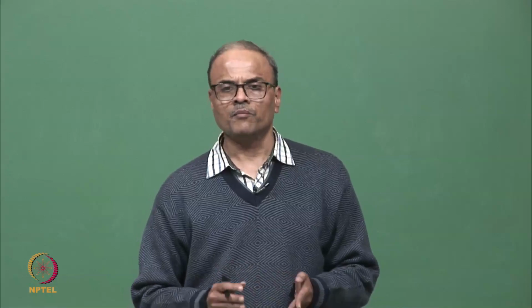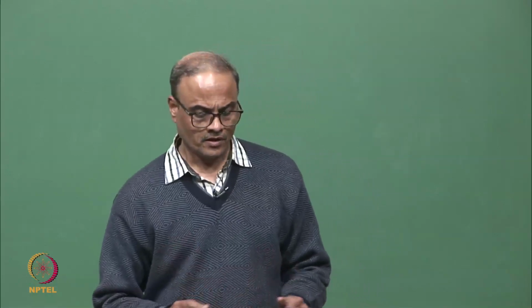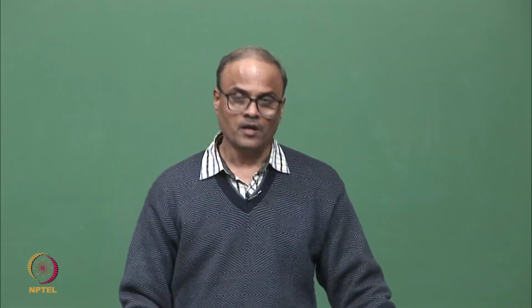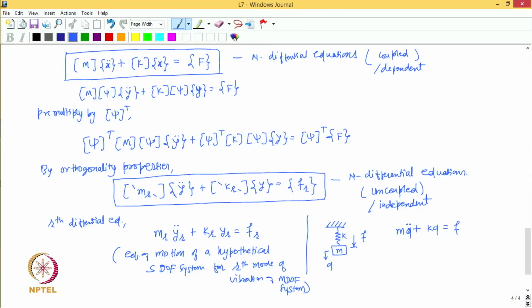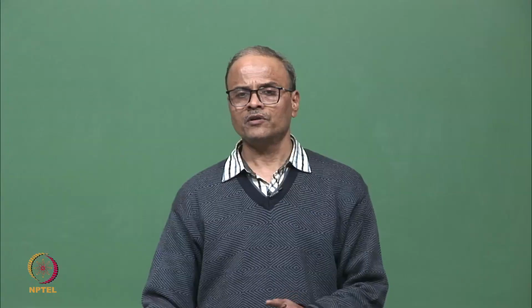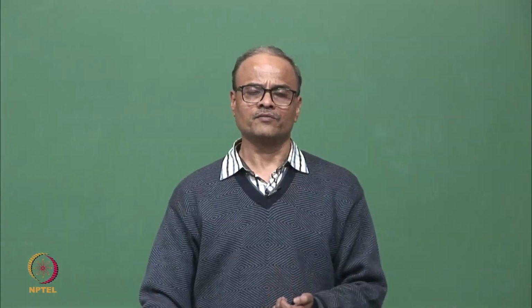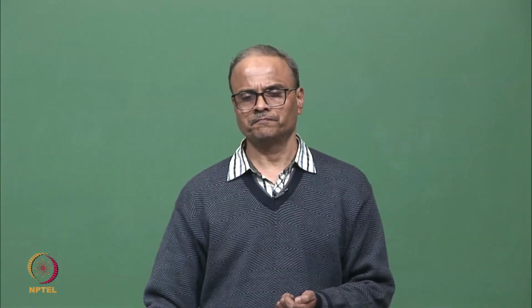Because we can look upon this as a hypothetical single degree of freedom system whose mass is Mr and stiffness is Kr, and because this equation corresponds to a mode of vibration, we refer to these quantities as modal mass and modal stiffness.